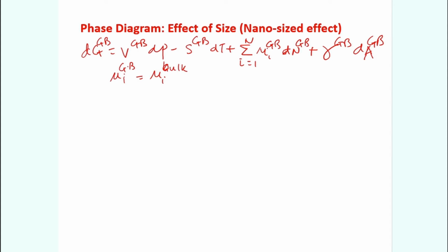Inside the grain, its atoms are in a bulk state, all the bonds are satisfied. Only the boundaries are not, right? Because haphazard arrangements of atoms are present, just like we have discussed in the case of a surface. So the interfaces are also similar types. There are dangling bonds or wrong bonds, all kinds of things are possible. Because of that, you have an energy increase, correct?